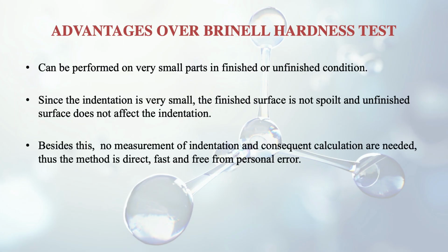Besides this, no measurement of indentation and consequent calculation are needed. Thus the method is direct, fast and free from personal error. Like in the previous one, we saw that we have to do the calculations and we have to derive the Brinell hardness number. So it is not needed here. So it's a much better process.